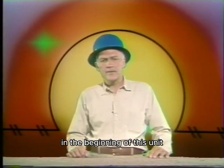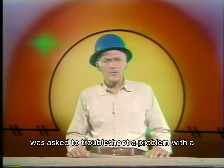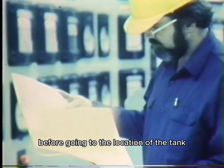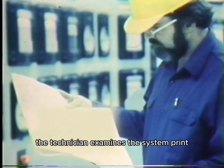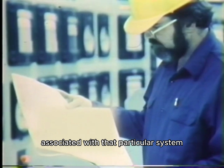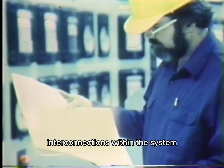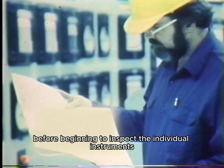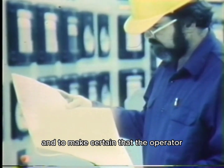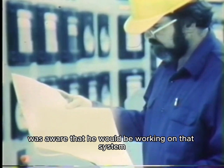In the beginning of this unit, a technician was asked to troubleshoot a problem with a fluctuating level in a clear well water tank. Before going to the location of the tank, the technician examines the system print to familiarize himself with the instrumentation associated with that particular system. He's careful to look for interconnections within the system before beginning to inspect the individual instruments. He discussed the situation with the system operator to find out more about the problem and to make certain that the operator was aware that he would be working on that system.